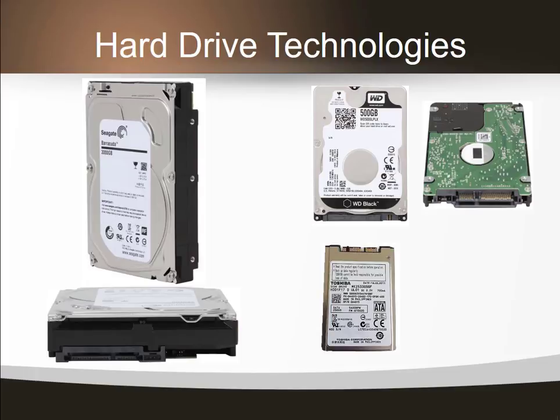On the left we have the relatively standard size for our desktop computers. That is the 3.5-inch size. And this one uses SATA technology for our connections. You have the 15-pin SATA connection and the 7-pin SATA connection. The 7-pin SATA connection is for your data, and you can see that here in this section. That is our 7-pin, and you can see that's denoted as an L shape.